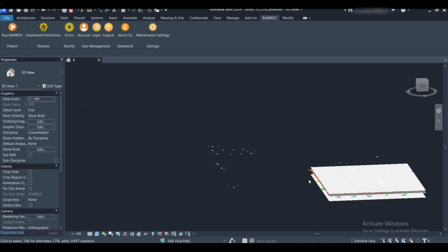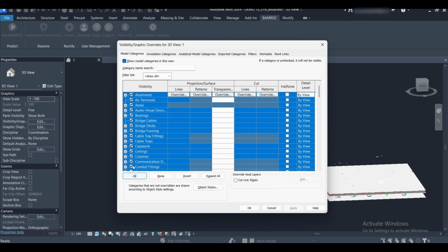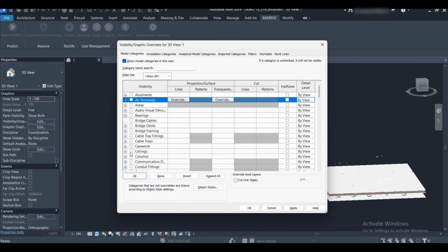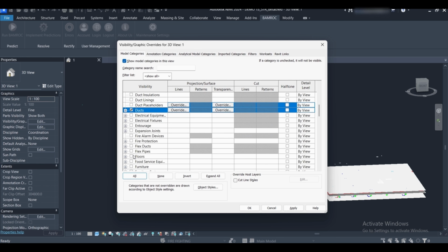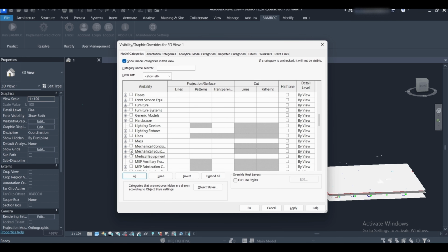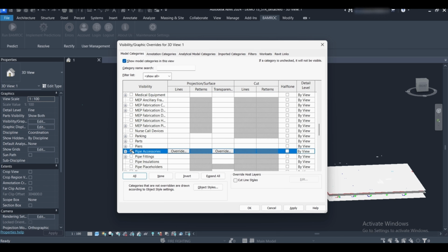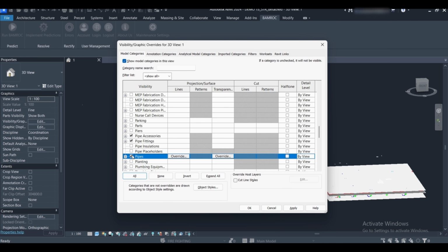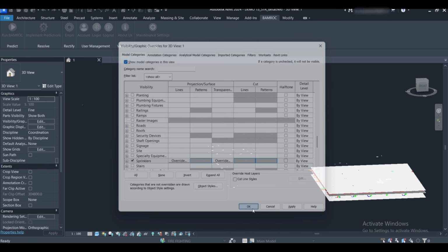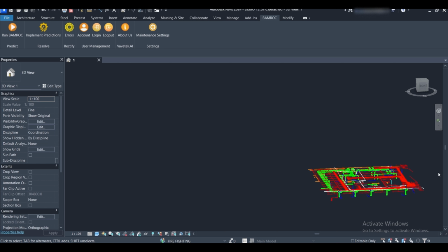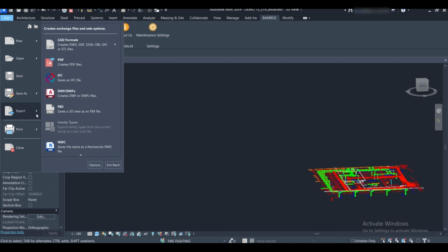Once your Revit is open and your project is loaded, here's what you need to do next. You'll start by selecting the first 11 categories in your model. These are the categories that are crucial for identifying clashes later. The categories include air terminals, cable tray fittings, duct accessories, duct fittings, ducts, mechanical equipment, pipe accessories, pipe fittings, pipes, and finally sprinklers. Once you've selected all of these, the model should be fully visible in your Revit workspace and you're all set for the next step.